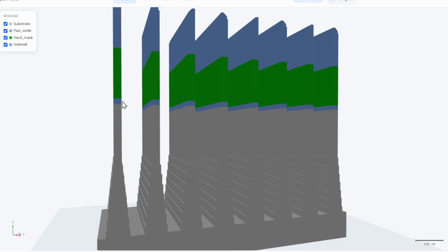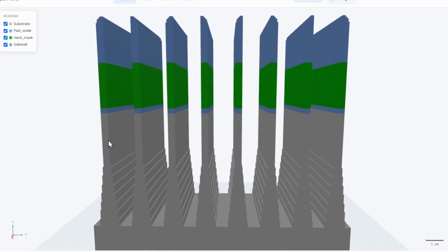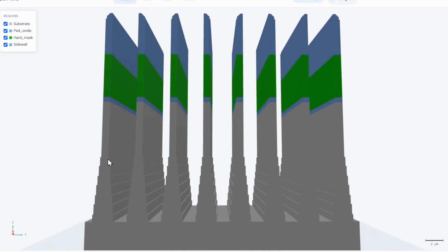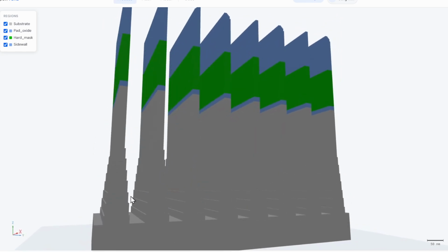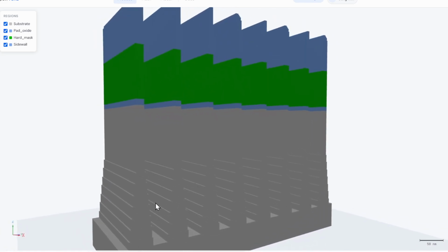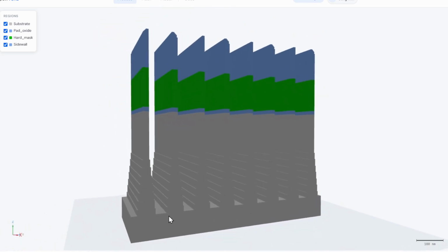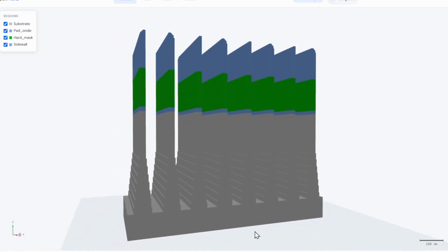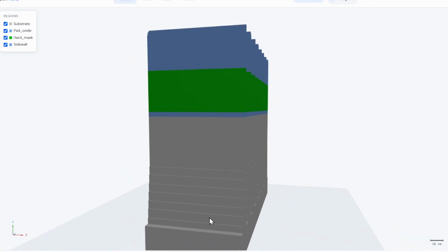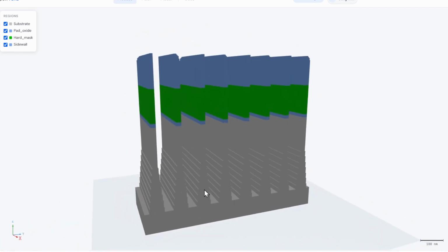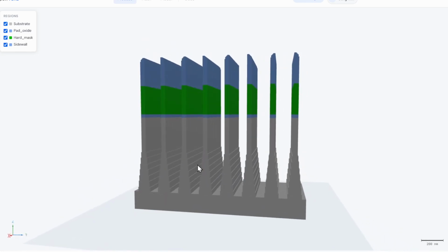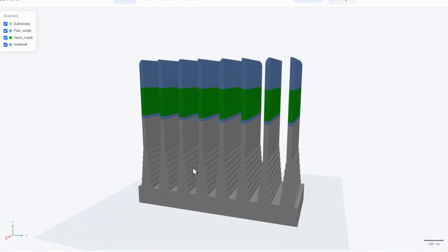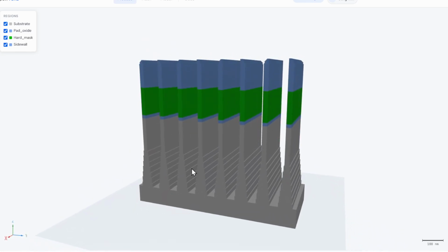One is an almost upright fin, and after that, to support this fin part, which will eventually become the channel, we introduce a tapered angle for our subfin structure, and beneath it we have just plain silicon substrate. So now we have a well patterned silicon fin, and now we have to do the next steps.